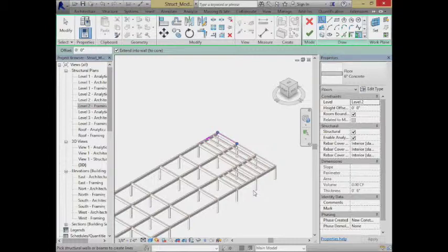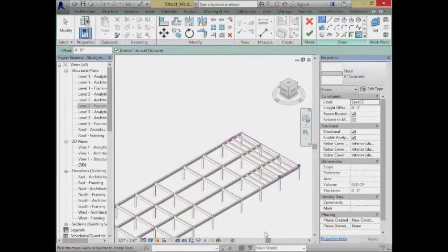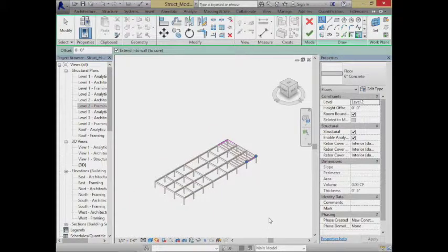It really depends on how you want to think about it structurally, whether it's one giant slab or you want to break the slab into smaller pieces that'll be analyzed separately structurally. I'll put it over the whole space right now. But what you're going to see, as opposed to choosing all the beams, is that whenever I have a big rectangle like this to do, what I almost always do is choose 4 boundaries.